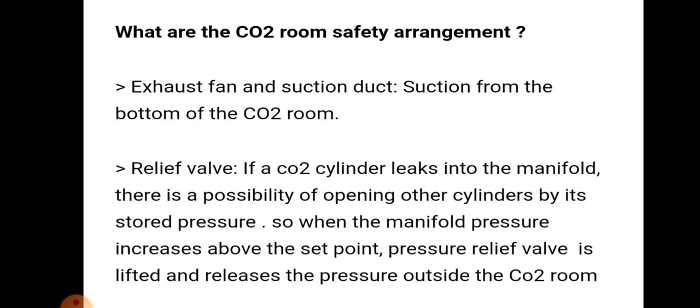Relief valve. If a CO2 cylinder leaks into the manifold, there is a possibility of opening other cylinders by its stored pressure. So when the manifold pressure increases above the set point, the pressure relief valve is lifted and reduces the pressure outside the CO2 room.